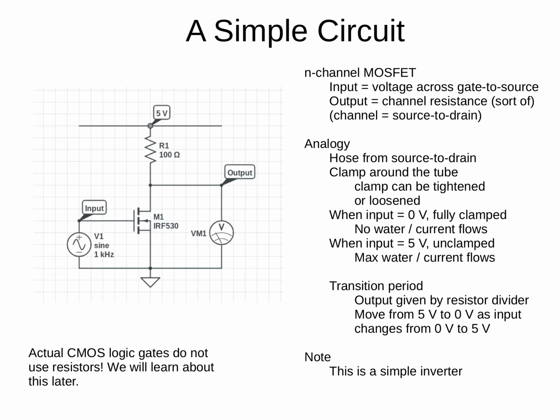Now of course in practice you'll get a very small amount of leakage current, but we can think of the impedance here as being in the order of 1 megohm or 10 megohms, etc., depending on the FET and the application. So for all intents and purposes, this is a very high resistance here. We call the FET being off if the voltage drop here is 0.